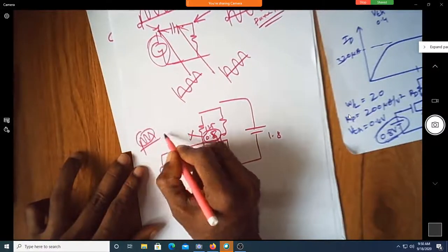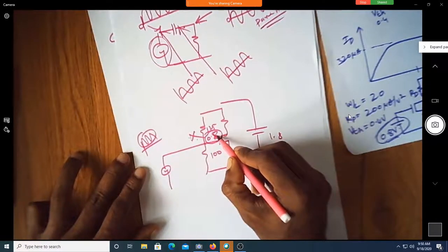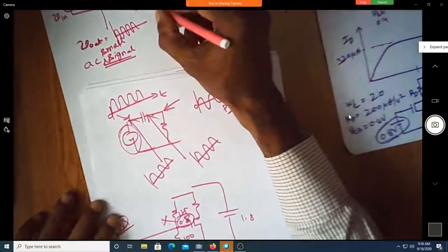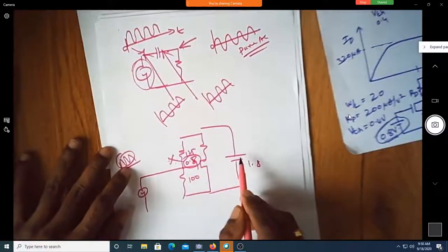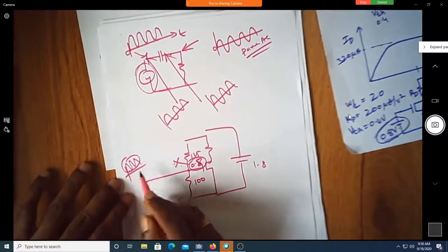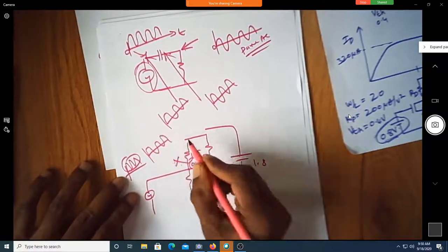Because you have some other voltage also coming. Why do you maintain this as 0.8? Because you want to use it as an amplifier where you want to have a current of 320 microampere. Is that affected by this input? Assume that you have this input, this is no more 0.8. Suppose you have a pure AC signal, will it be 0.8?